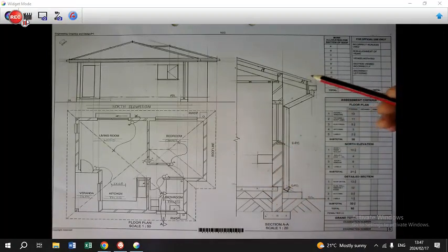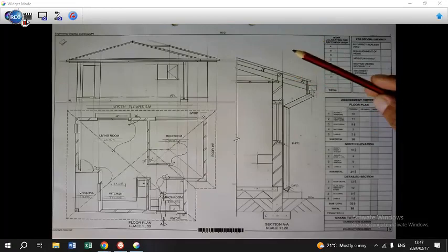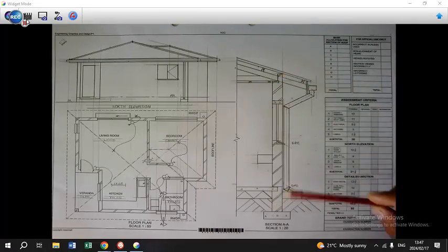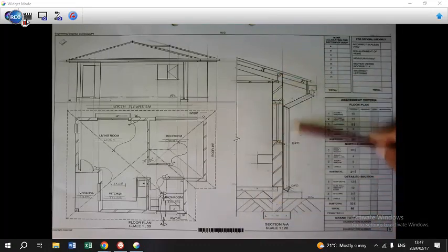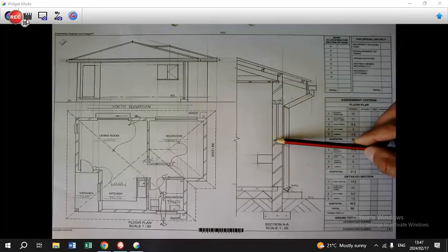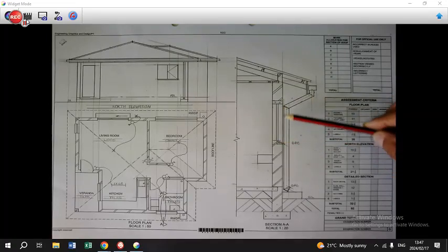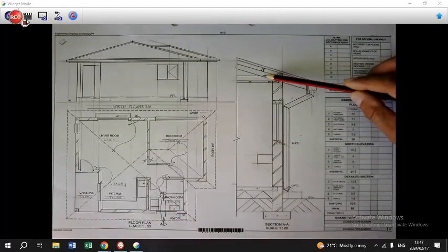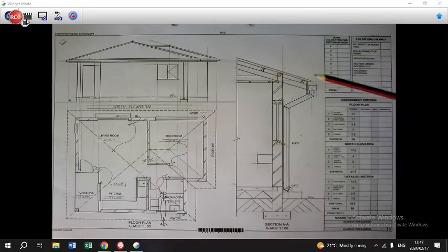Grade 12s, we concluded the detail section where we have looked at each of the different phases in detail. We started with the foundation and the wall, and we have the window with the lintels, the window frame, the window sill, inside and outside. And then we went on to phase 3, which is your roof with all your different components, your truss, your brandering, your purlins and your sheeting, including your fascia board, gutter and rainwater downpipe.